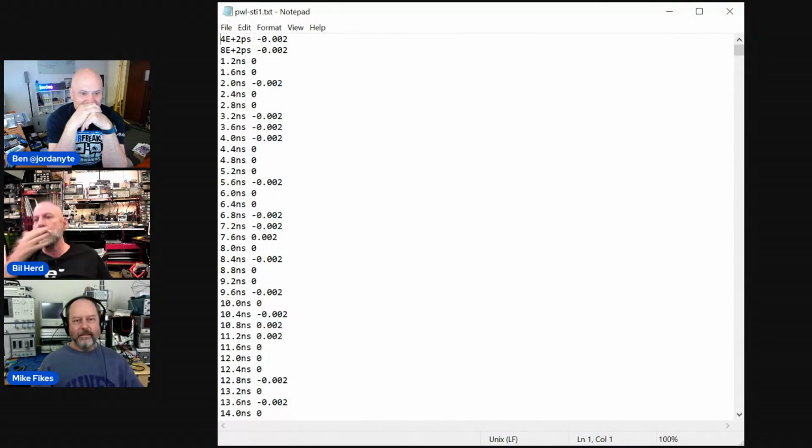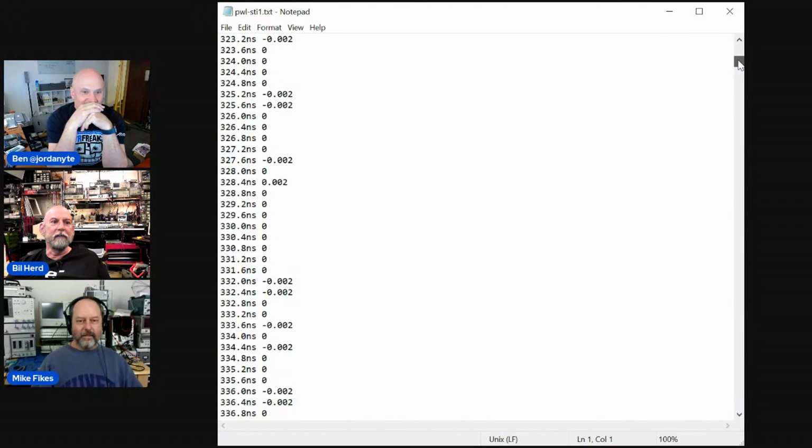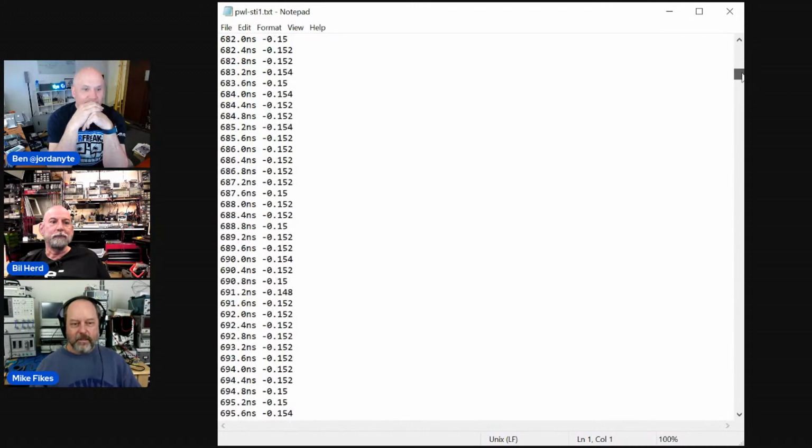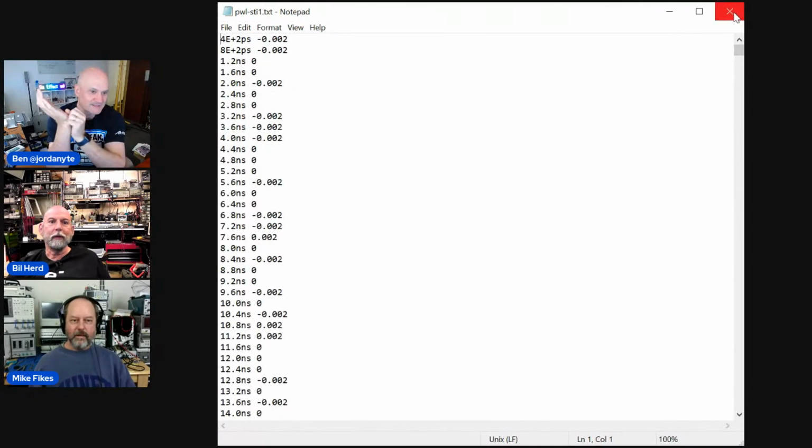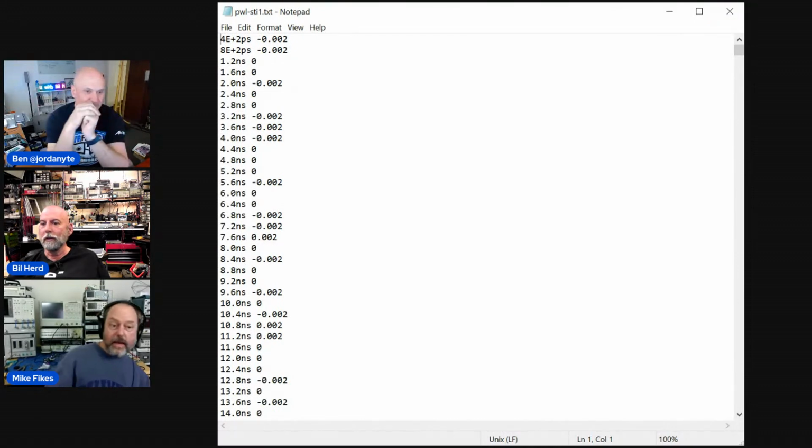So when we're talking about piecewise linear, we're talking about a file that looks like this that basically draws the values for you. As you might expect, it's fairly trivial once you have a scope trace to convert it to that format. It's just time versus value, right? Yeah. Especially my scope, Bill can't get his to do it, but mine will give me a CSV, and writing a script to do that is pretty much trivial. Then you kind of have to get the time base right.